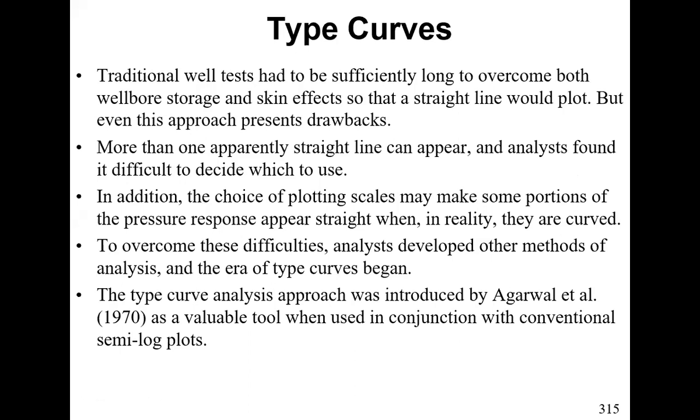Up to this point, we have illustrated the use of conventional semi-log plots. And you've seen how to analyze data in the middle time region, that is data that fall into the infinite acting radial flow period.